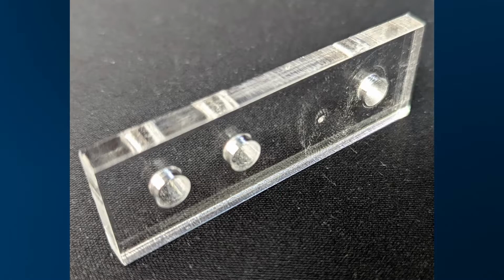So, since we're talking about plastics, we should also talk about compatible materials. You can find large lists of the things that you can and cannot laser cut. Some companies will sell things that are specifically laser compatible. There are several big things to worry about, but one of the biggest and most common is chlorinated compounds. So PVC is a very, very common material. You do not want to put that on a laser cutter. Essentially, anything with chlorine you want to avoid putting in the laser cutter.